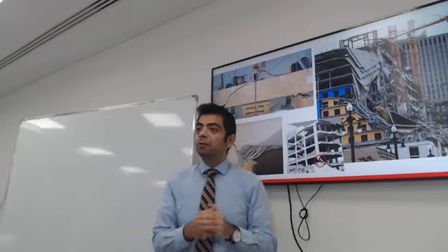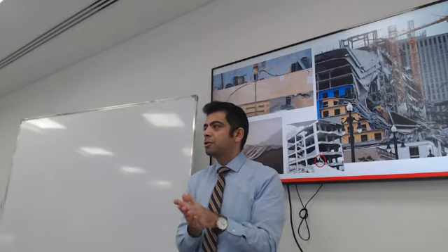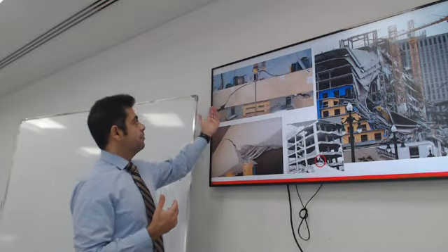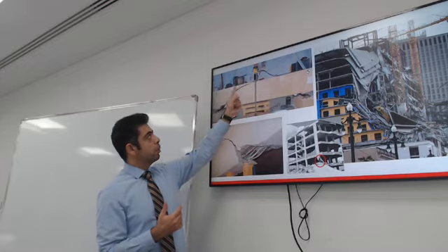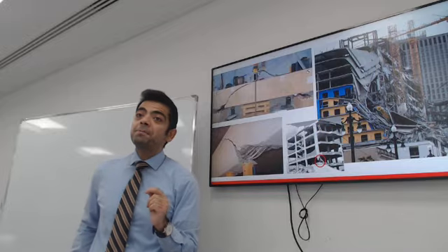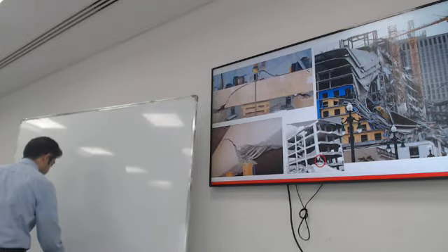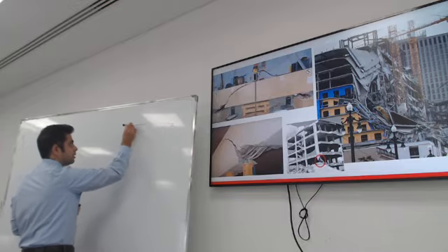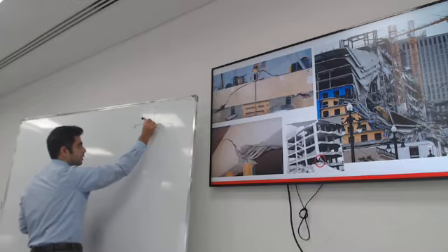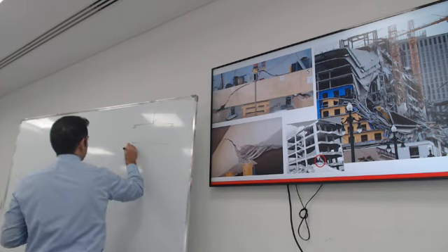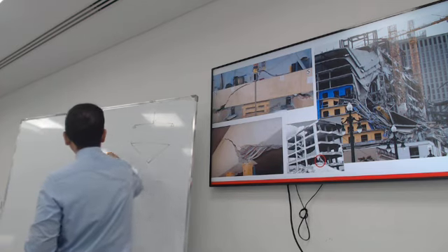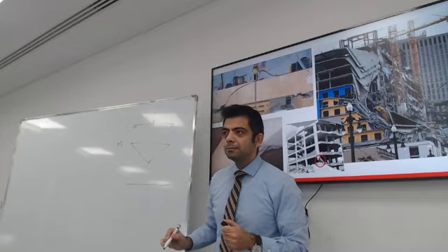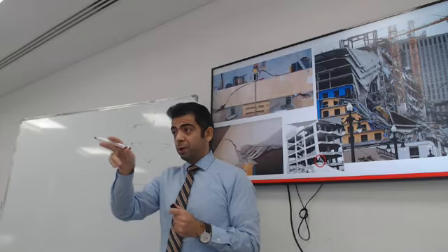Before we get into the angle of the crack and the angle of the truss, let's visibly understand what shear is. If you have a simply supported beam with a point load in the middle, what do you expect the shear diagram to look like? A V? You're talking about something like this? Yeah, that's the bending. Thank you very much. So how will the shear look? It's a rectangle, up and down.